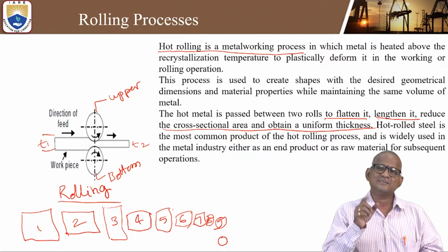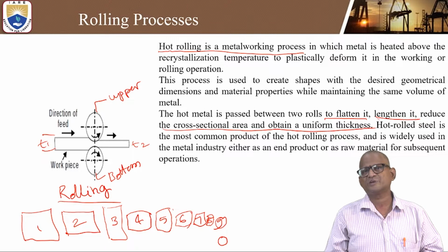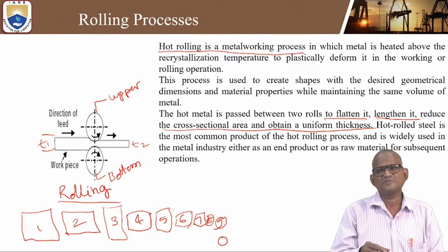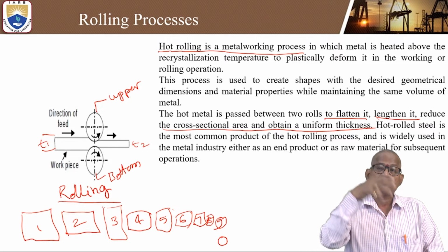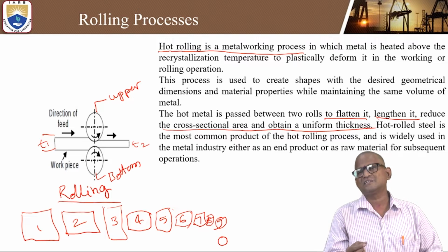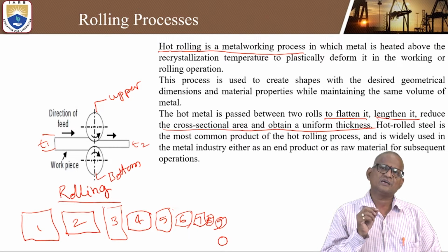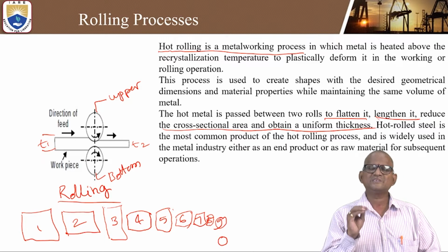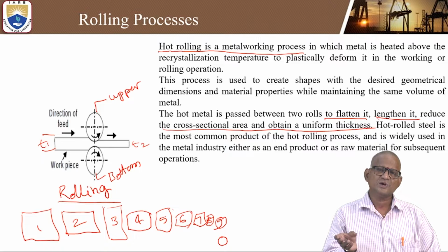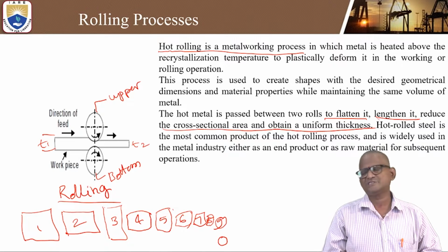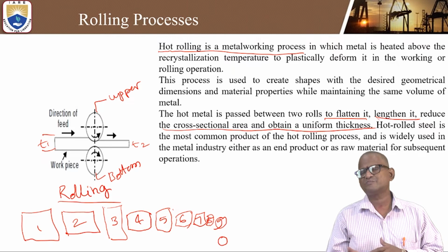That is why that is the one disadvantage in the cold working process. A lot of force can be required, and sometimes pressing machines can also be taken into consideration to change the thickness. So that is why, in a cold working process, it is only a single process, only the pressure tonnage will be more. The initial cost is high, but to compensate for the cost, the production rate can be more.